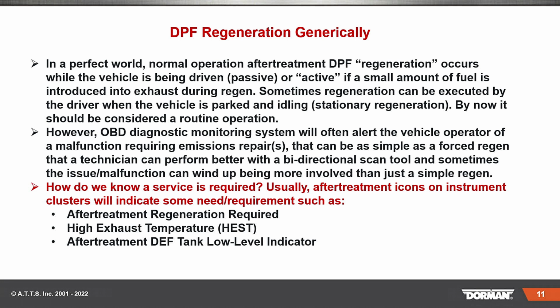How do we know a service is required? Well, it's not rocket science, but usually the after treatment icons on the instrument cluster will indicate some requirements, such as after treatment regen. Don't forget, you have the HEST, the high exhaust system temperature, which might come on, and of course, boy, I gotta tell you, all day long, the after treatment DEF tank low level indicator. I shouldn't make fun, but how could you not know that your tank is getting low? But it's usually the education part on the other end, not us guys, okay?